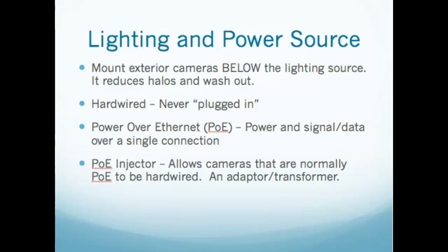Now, in many cases, perhaps you're not going to plug it into an Ethernet port, or maybe you don't have Ethernet out that far and you're going to run it over some other way, but the camera is set to work as a PoE camera, right? That's the camera you have. You're going to reposition one. Let's say you're going to take it from someplace that's on your network in your business, and you're going to move it out to a new building that doesn't have a network in it yet. You can get something called a PoE injector, power over Ethernet injector, and it essentially will turn that camera into one that you can hardwire or plug in. It's an adapter, and they do make those.